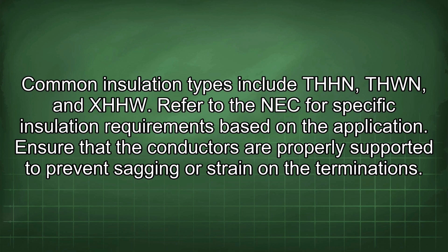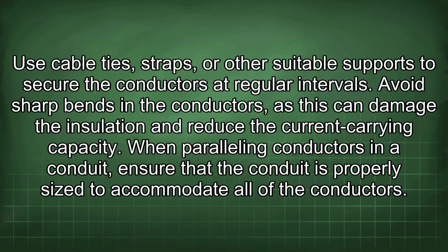Ensure that the conductors are properly supported to prevent sagging or strain on the terminations. Use cable ties, straps, or other suitable supports to secure the conductors at regular intervals. Avoid sharp bends in the conductors, as this can damage the insulation and reduce the current carrying capacity.